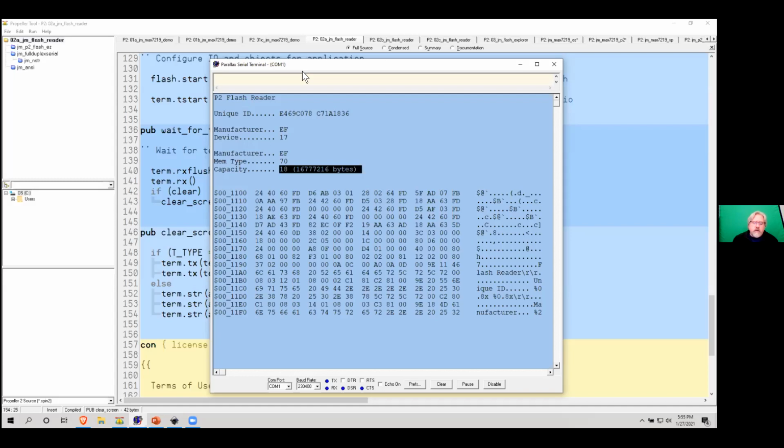One of the chunks of data you can deal with from an erase cycle in the flash is 64K. So I assigned 64K blocks to each program, and when they want to update their program, which again will be very infrequent, it just erases that 64K, and then they have that much space to record into.